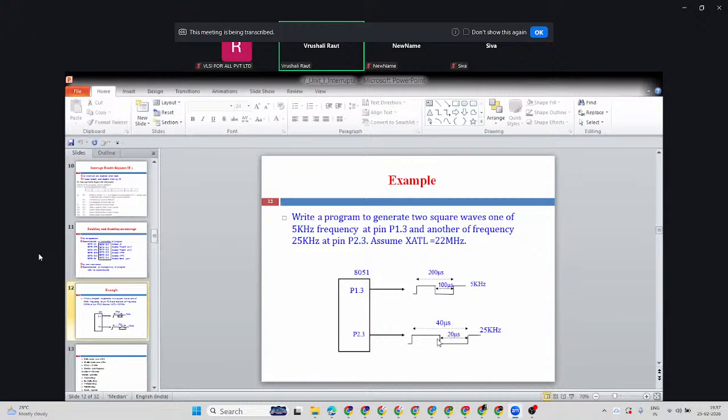So you have to generate the interrupt after every 20 microsecond. Who is generating the interrupt? Flag of the timer is generating. Which timer are we using here? Timer 1. Its flag will give us the interrupt and we will change from high to low, low to high, and so on. We are generating the frequency. This is how we are using two internal timers. Do you got it? I want you people even to take it down and try the program in C for this. You will get the idea what we are using here.